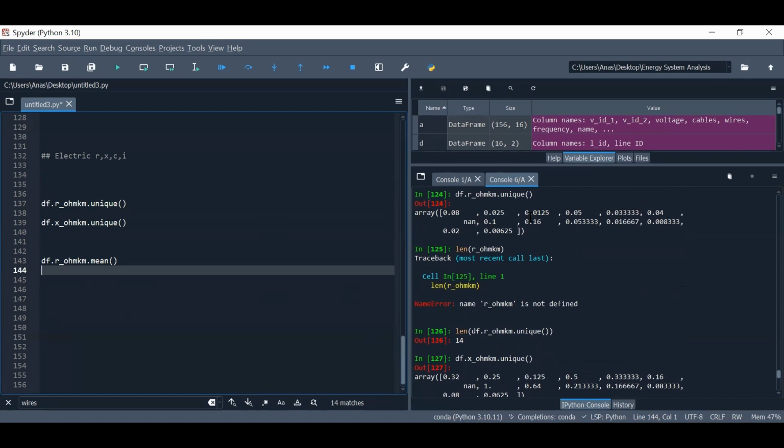But we know that if you know the background behind this data or the background behind transmission line calculations, you know that there is standards from manufacturers that they have this standard with this R ohm per kilometer, or this X ohm per kilometer, or this nanofarads, or this capacitor, or shunt capacity, or this thermal current, or maximum thermal current. So somehow it's standardized.